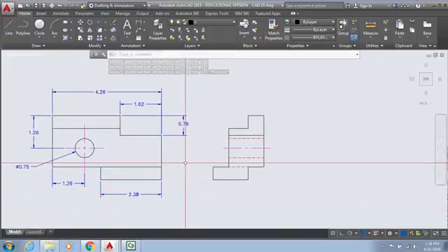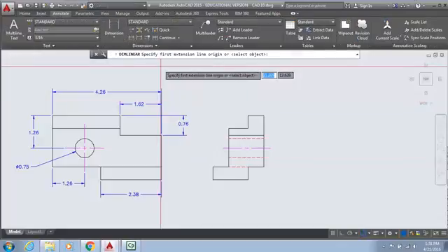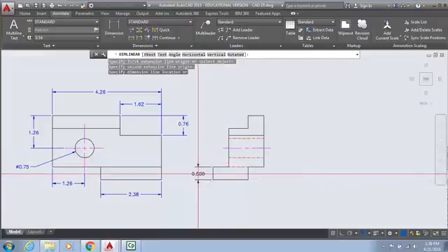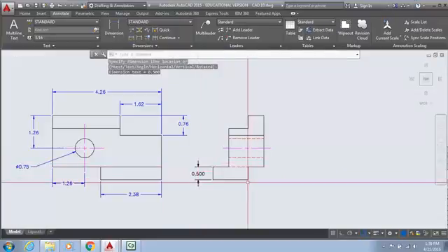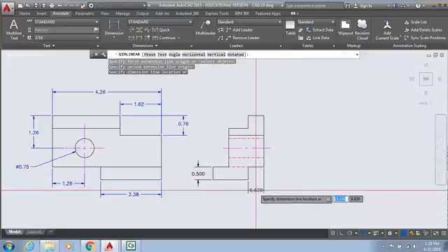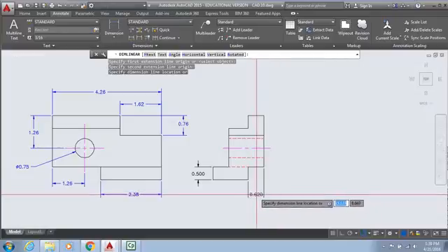So let's put dimensions on the side view. Go back to annotate here. We got a dimension here to here. That's a 1/2 inch. We go from here to here, 0.62. Now if you can't fit it in, I think it'll fit in, you can always drag it outside. That's not too horrible.